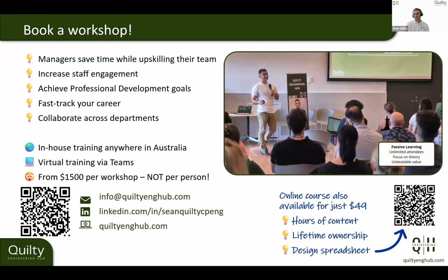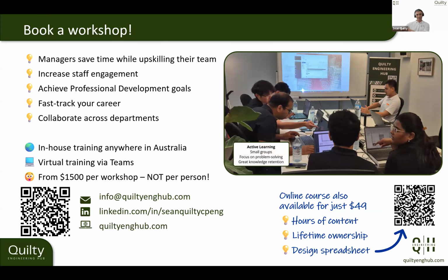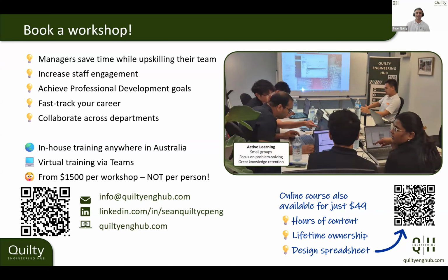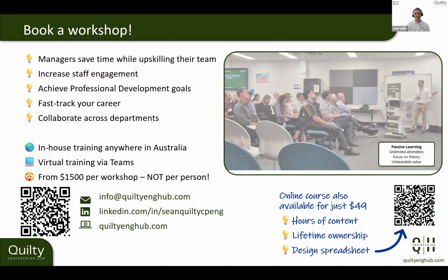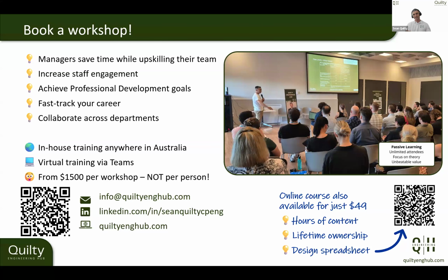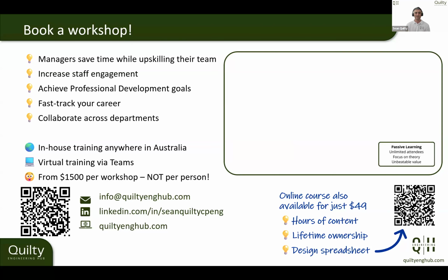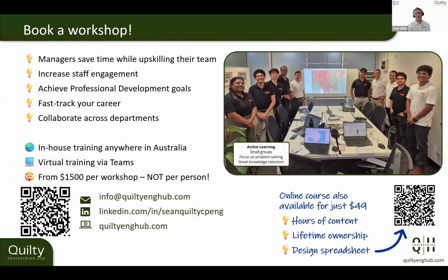You can create composite Mannings values. If you have a bit of rock and a bit of concrete and a bit of grass, you almost just mush up that section into a composite section and use a theoretical Mannings value. So it's not as smooth as all the concrete sections, it's not as rough as all the grass sections, and you find this midpoint somewhere. So yes, you can. Yep.